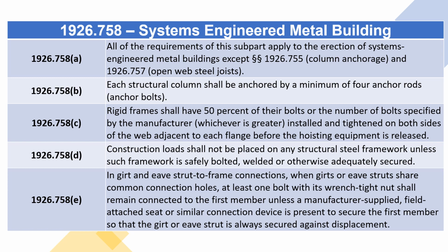1926.758 D. Construction load shall not be placed on any structural steel framework unless such framework is safely bolted, welded or otherwise adequately secured.